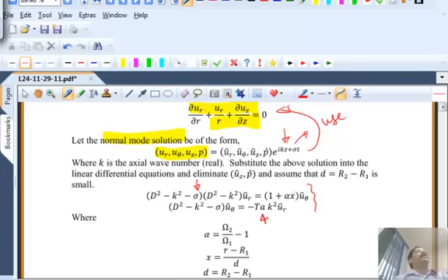So put various values of Taylor number and get out the sigma and check whether the real part of the sigma is negative. Then you know for that Taylor number the flow is stable. You will not form cells, you will have just one-dimensional flow. But if there is any value of Taylor number for which this is positive, then the cellular flow will develop. And that was done by Taylor in 1923.